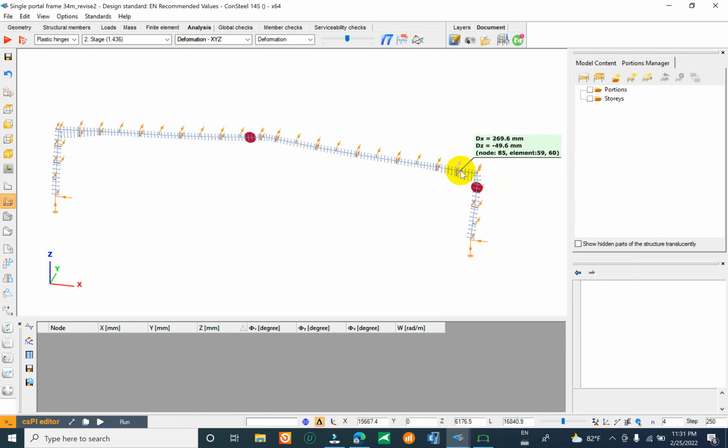At least you have to restrain this one and this one. So you have at least two supports and one out-of-plane restraint here, 1, 2, 3, using a tube section or a rectangular section to restrain from one plane to another plane and the location.